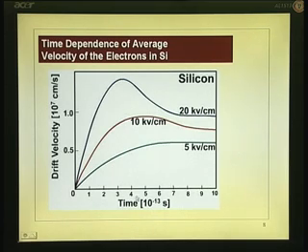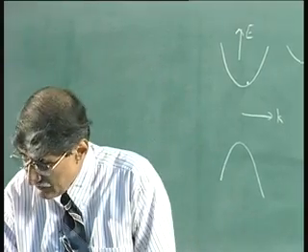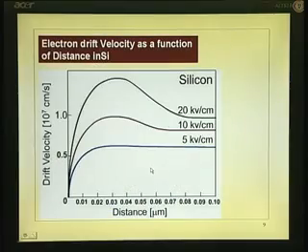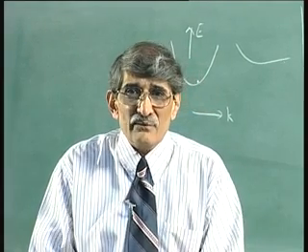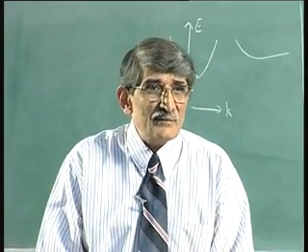So, it is less than a picosecond, about half a picosecond, whereas in gallium arsenide it was a picosecond or more, and distances in gallium arsenide were 0.5 micron, indium phosphide 1 micron, up to that you have the velocity overshoot effect. In silicon you can see this is 0.07 micron, much less than 0.1 micron. So, if you want to get the benefit of this velocity overshoot effect with silicon, what channel length should you talk of? Less than 0.1 micron.